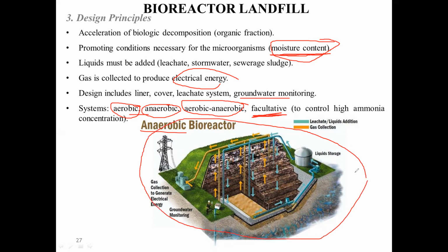In the landfill, you have a composite clay which is going to be laid and lined. Then you have this thin layer of black sheet, that is nothing but your liner, over which you are going to be putting the clay, right? Then boulder particles are going to be segregated. Then we put the surface, the liners, again a composite liner, over which you put your waste. While putting this waste, we are going to provide some pipes.